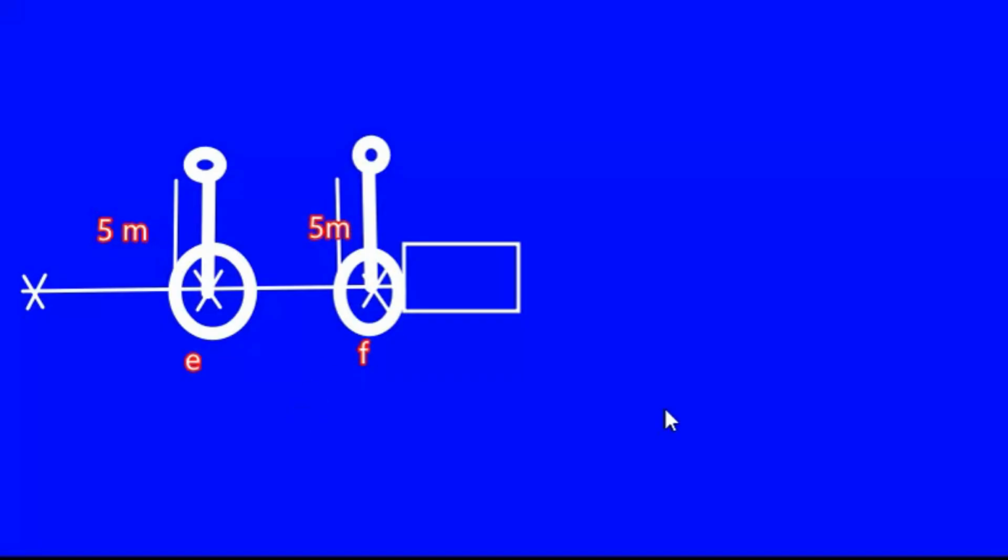Now since these two are 5 meters each, now what we can do, since we have already these 2 points which are at 5 meters here, right? So these are the 2 points that are 5 meters. You can place a cross staff again back somewhere here, and after placing the cross staff you will keep a ranging rod at this point over here, and when you keep the ranging rod over here you will easily be able to mark this point onto the ground. So you put a ranging rod here, right?